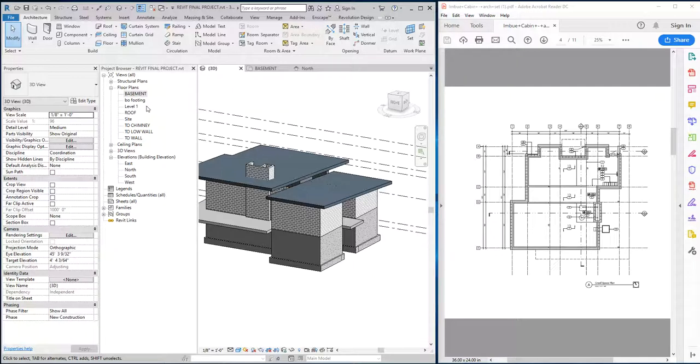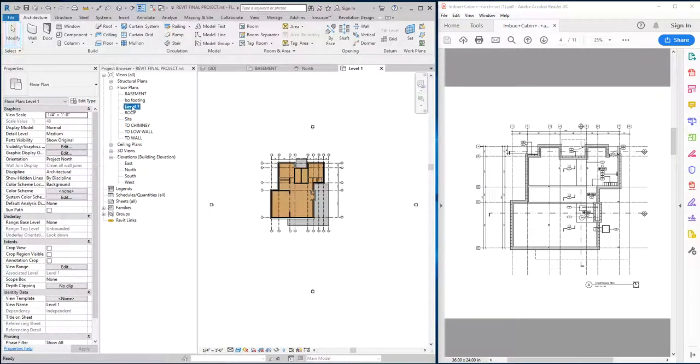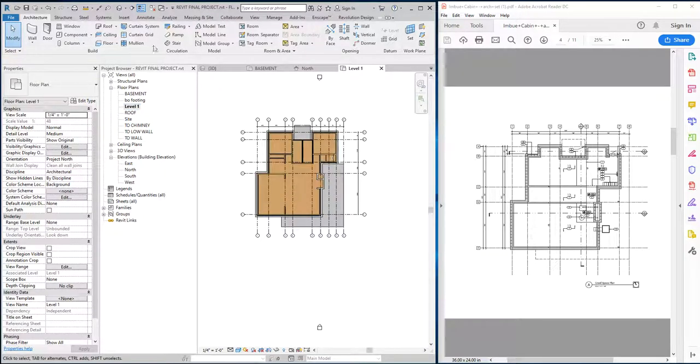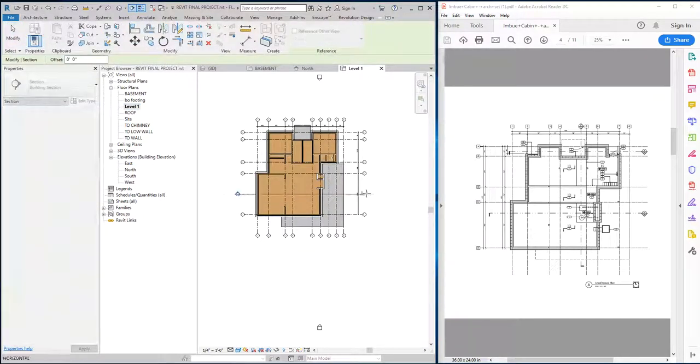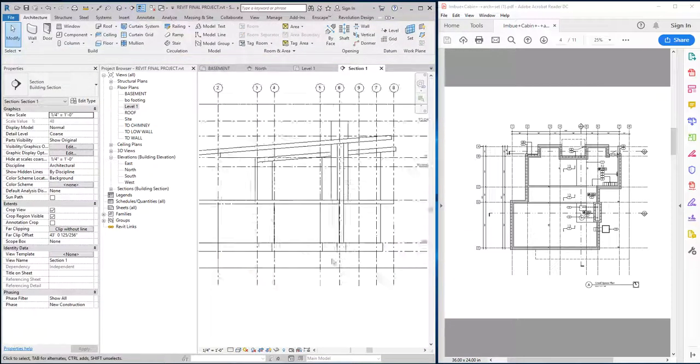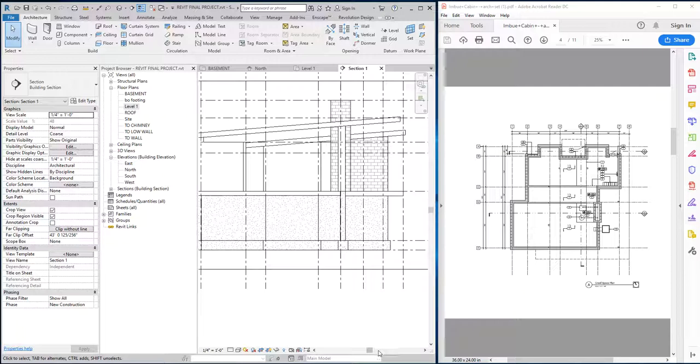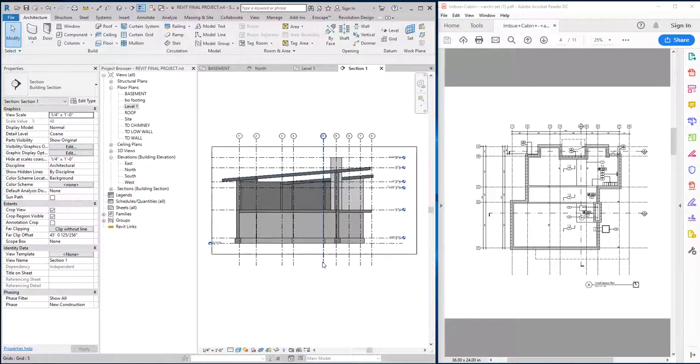So now if I wanted to, for example, go to level 1 here, right? And if I wanted to add a section cut here, click, click, I can see my little footings down there. Okay. So there's no magic to creating footings, right? I think that it's just a different way of thinking about it, but now these are highly editable. They're easy to manipulate. They're architectural items showing design intent, right? And it doesn't confuse anybody, which is what would happen if you use the structural elements, essentially, even though they're really easy, right? Okay, we'll talk about that in a second.